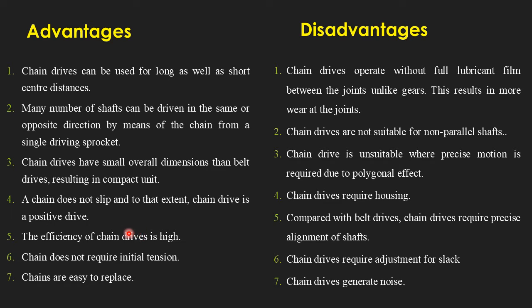Regarding the efficiency, the chain drive is very high, up to around 96 to 98%. But in order to maintain that efficiency, the chains need to be properly lubricated. If proper lubrication or regular maintenance is not there, then the efficiency will come down. Even the initial tensioning, that is regular maintenance with tensioning of the chains, needs to be done, or else the efficiency of the chain drives will come down. Otherwise the efficiency is very high. So those are certain advantages.